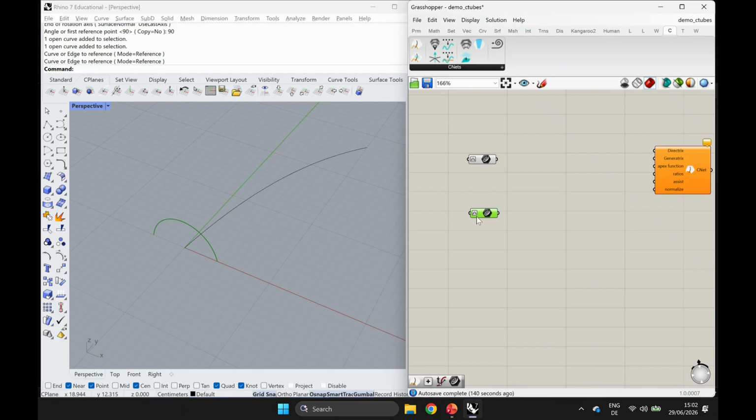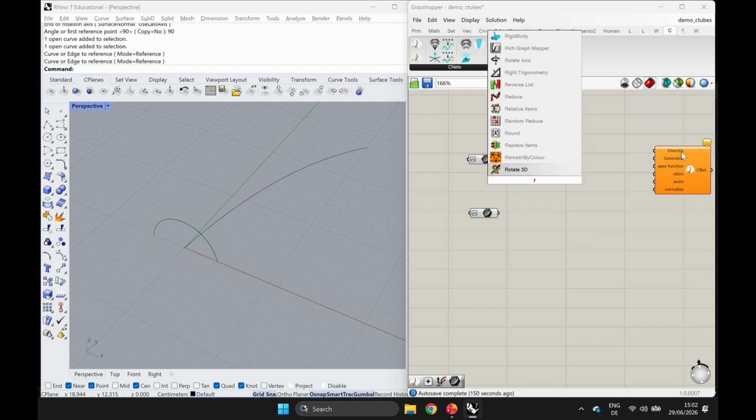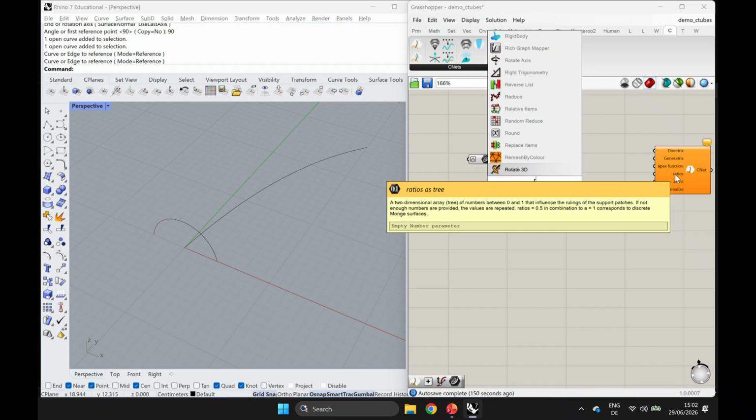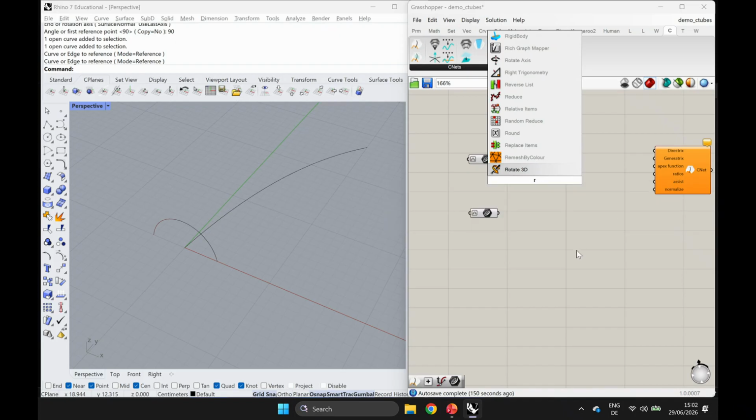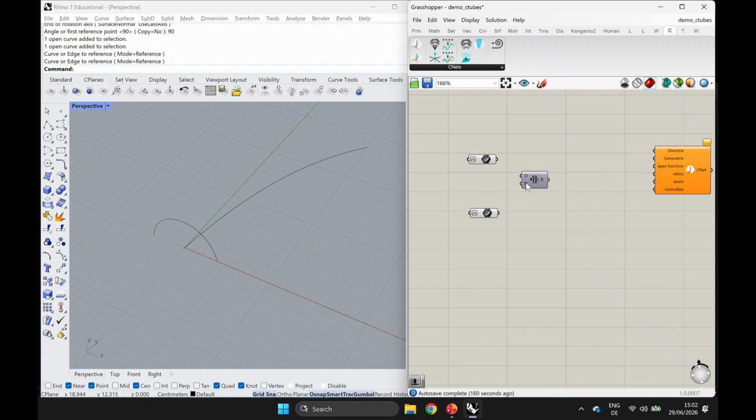This can be done quite conveniently just by a few clicks. Because this component takes a polyline as input, I will just sample this curve by defining a range. This can be done quite conveniently with another component. Here, this is the domain of the range and the number of samples or steps. And here I want to have somewhere between 3 and 100 samples because we will just play with it.